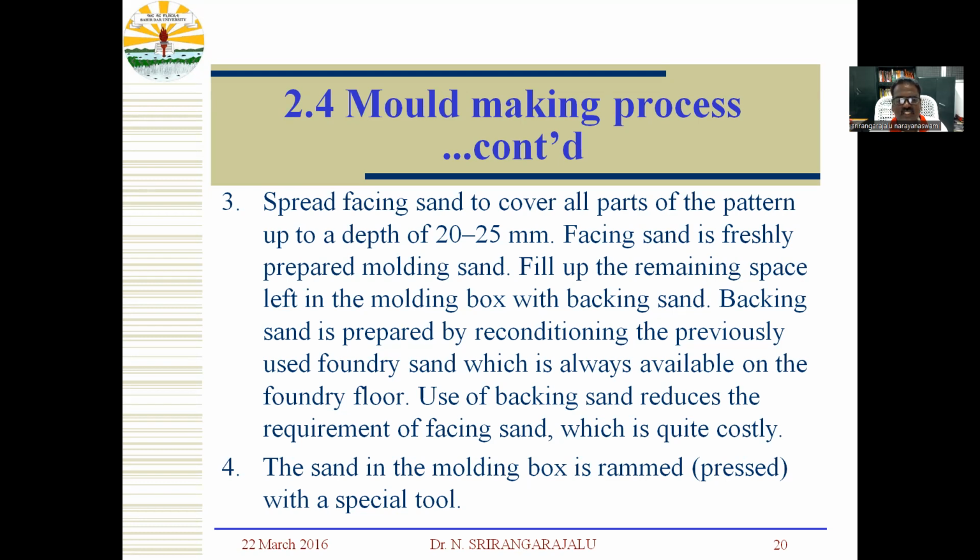Fill up the remaining space left in the molding box with backing sand. Backing sand is prepared by reconditioning the previously used foundry sand, which is always available on the foundry floor. Using backing sand reduces the requirement of facing sand, which is quite costly. The sand in the molding box is rammed and pressed with a special tool.